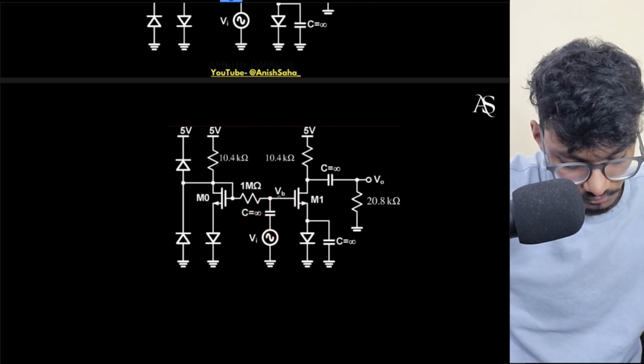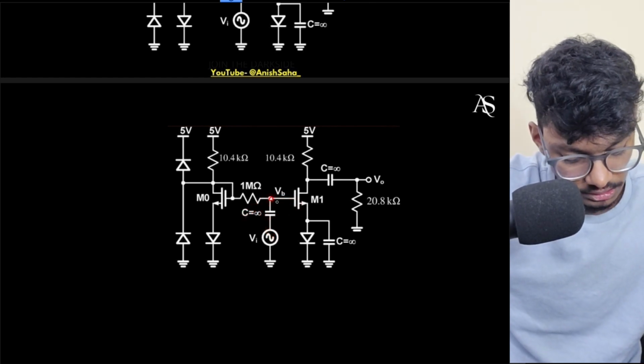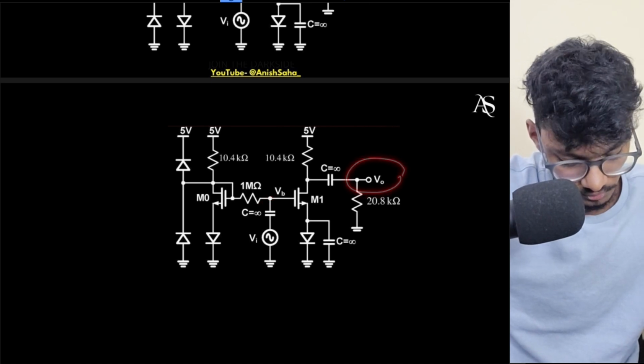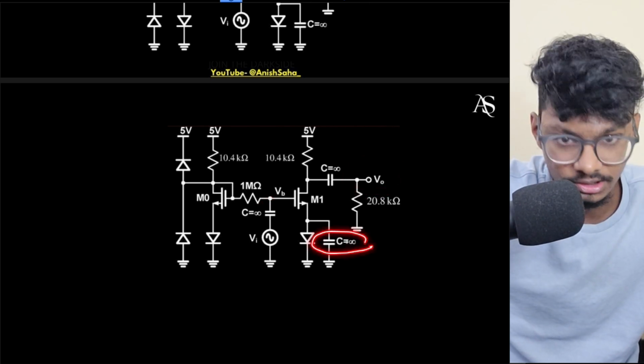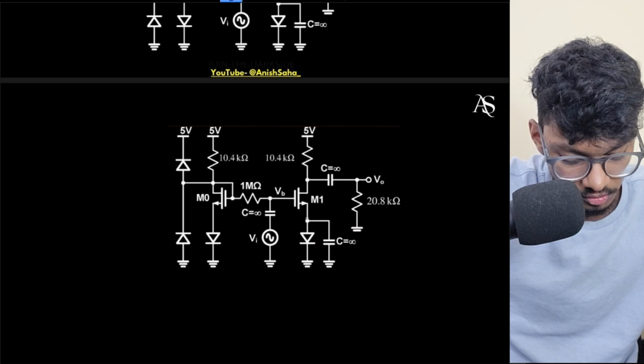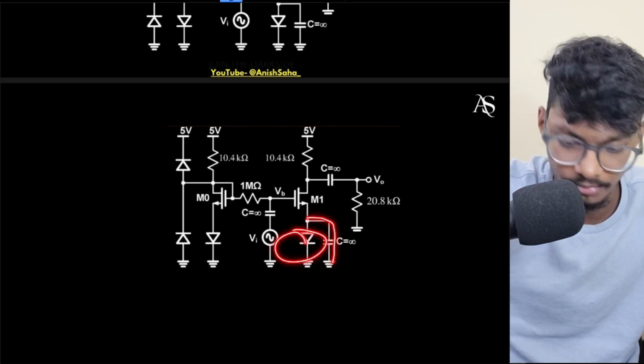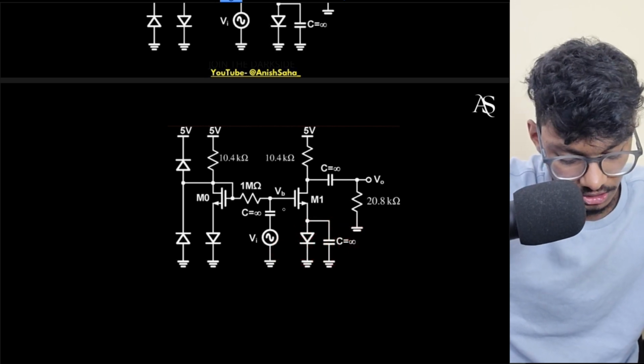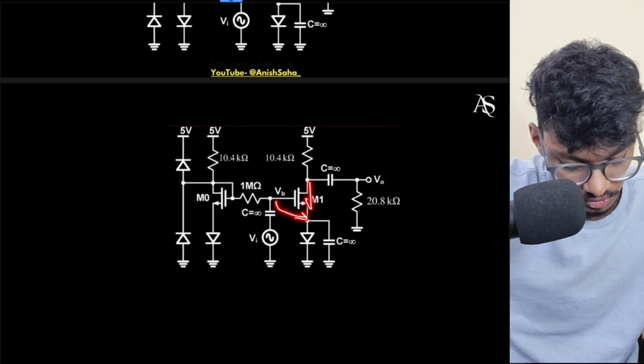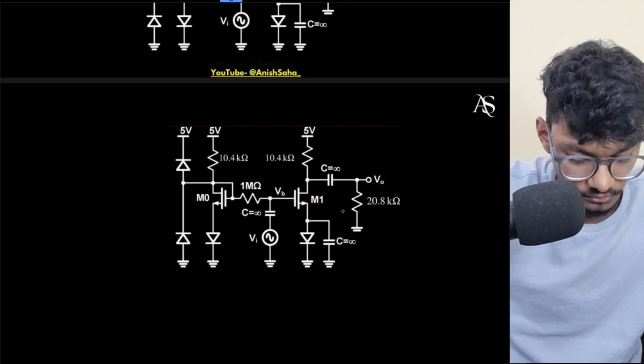Now if my Vi signal is here, how will I identify my VO? At small signal, this will again be a short circuit, right? 0 ohms impedance. So this diode will simply be short circuited. This diode will not come into action, only this capacitor will be present. So I can directly say the current through this MOSFET will be GM1 into Vi.